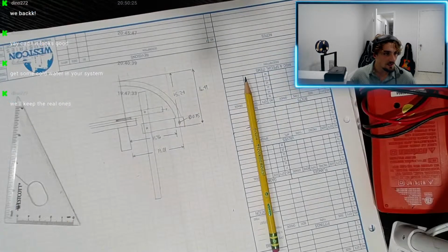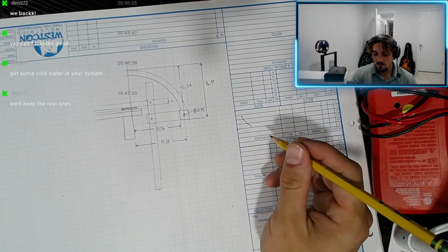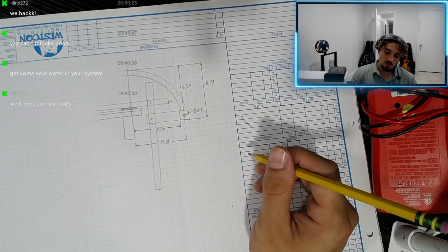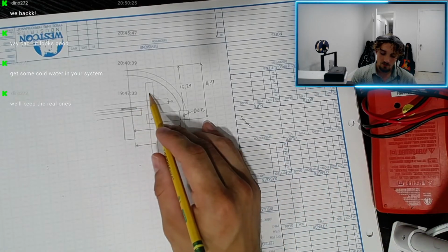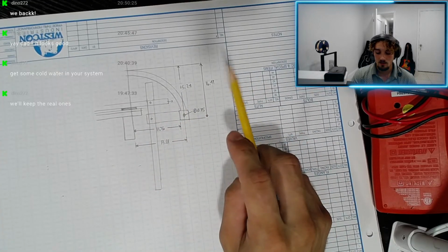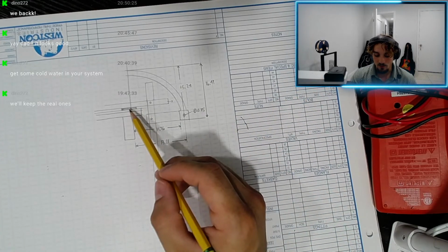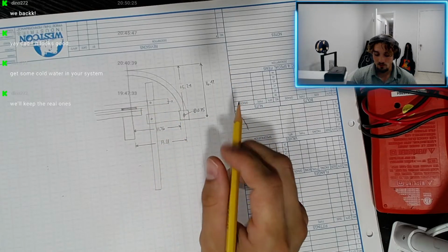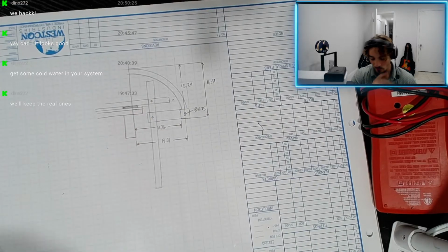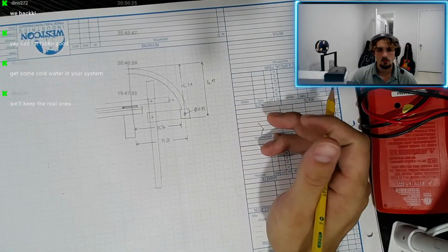Alright, so considering our design, 11.6 is our distance. To get the greatest leverage, we truly want this as far back as possible, but we're limited by our distance here and the tracks there. We will absolutely need an adapter from the glider to the rack of the rack and pinion mechanism, so really there should be one more slab in between here. But those are things we worry about later. It's not really important now.